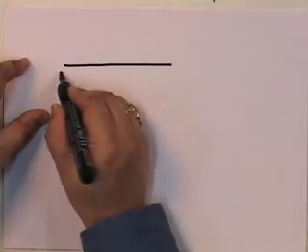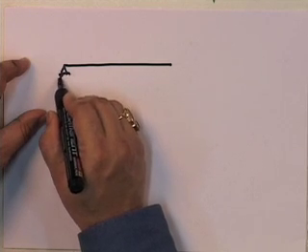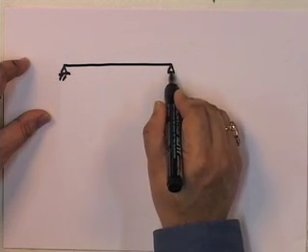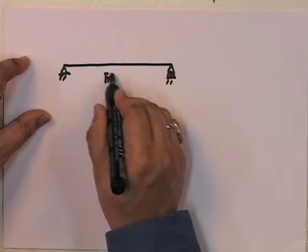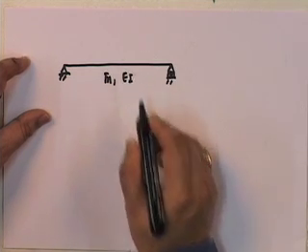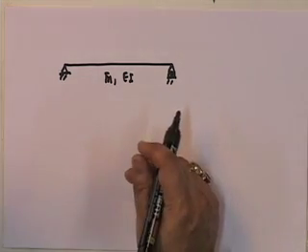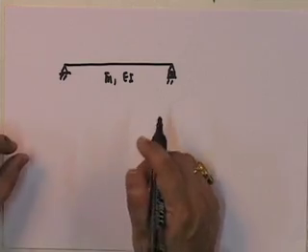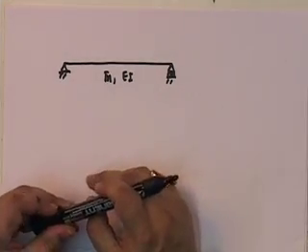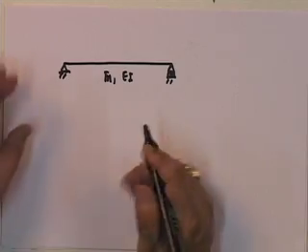So I will solve a very simple problem, and that is that of a simple beam, constant m bar, EI, no rotatory inertia, no shear distortion, okay, only flexural deformation and point mass for the cross section.